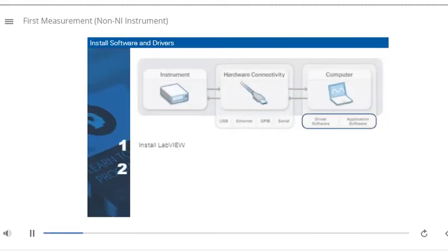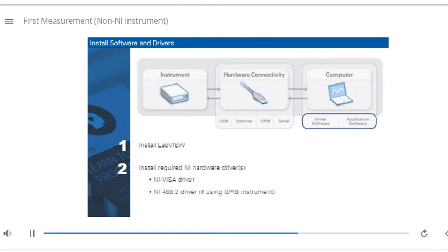First, install LabVIEW. Then install any required NI hardware drivers. You must install the NI VISA driver. If you are trying to communicate with a non-NI instrument using GPIB connectivity, then you must install the NI-488.2 driver, which automatically installs the NI VISA driver also.